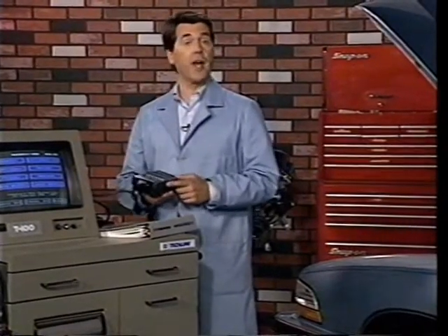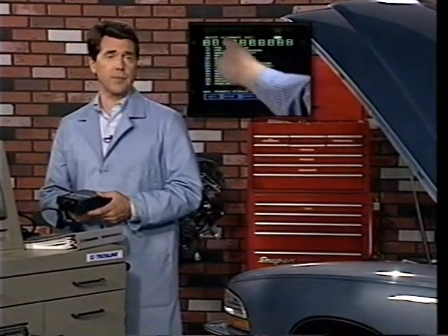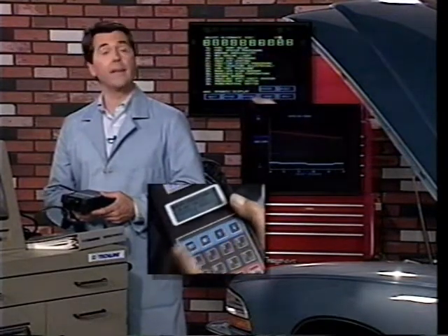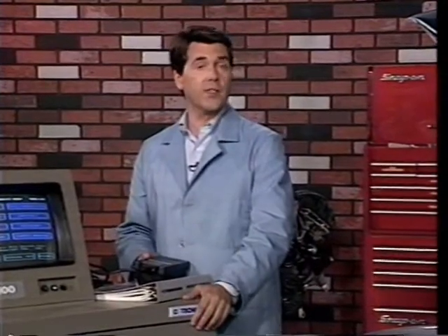Scan tools are designed to help technicians find drivability problems. Knowing how and when to use FIPS, Data Plotter, Snapshot, and data pairs helps technicians make better use of their time. Remember, the upcoming drivability programs provide detailed information on engine families. Specific diagnostic routines and troubleshooting tips for these engines will be examined in these programs. By using diagnostic scan tools in the way they are intended, we can keep Buicks on great American roads and out of the service bay.